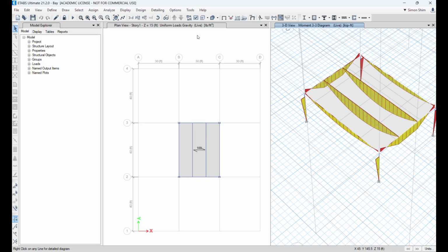So if we have a live load of 100 psf times a tributary width of 10, it is 1000 pounds per foot, 1 kip per foot, times the length. W, L is 40, so WL squared divided by 8 is the maximum moment for the uniform load, so you should be able to calculate the moment, and shear as well. All right, so I want you to practice up to this.